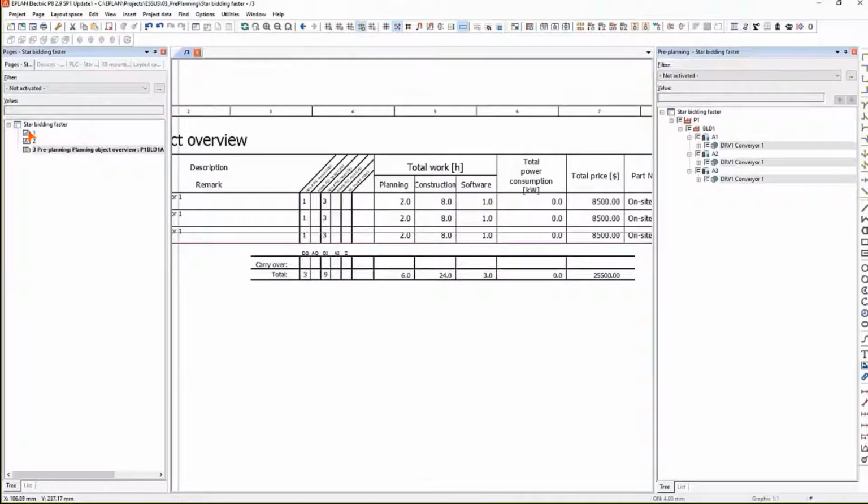I just have an understanding of the control systems that I'll need. I also have a number of I/Os or signals needed for that particular system. So there I can already start sizing my PLC system and maybe go to the various different PLC vendors and asking them what type of PLC could support that type of system.